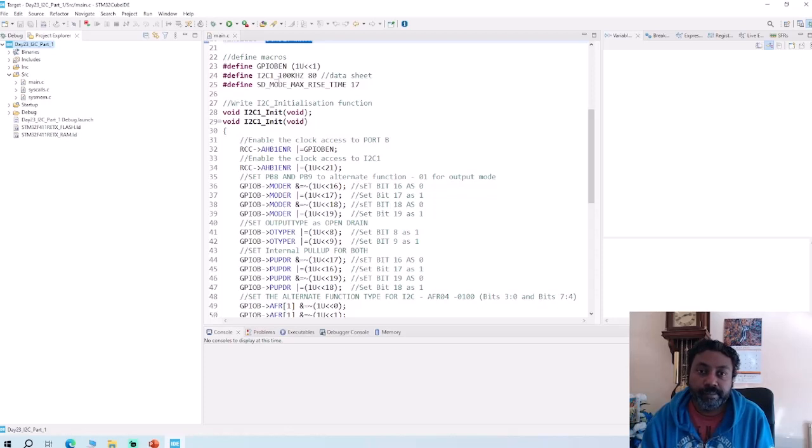So you need to define, and to write the define, this is the example, hash define. This is how you've got to write it. As you know, GPIO port B is bit 1 in the data sheet. I will also open the data sheet, just one sec, I can show where that is. I'm just opening my Microsoft Edge, just one sec. So you need to enable bit 1 as 1. That means enabling the GPIO port B.